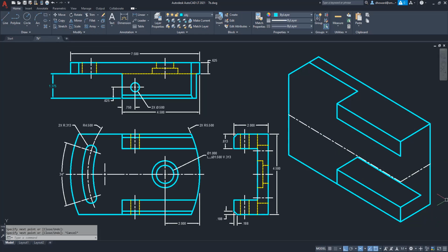That happens to line up with that center line almost perfectly, huh? We can join this with this upper piece if we want by pulling back that distance, which is the 1.375, and then closing it there. Of course, that is not going to stay that way because this side is going to become an arc, but temporarily we can just do that. I'm going to get rid of that center line temporarily because it's kind of getting in the way. Okay, so we have the back, or I should say the right side of this box kind of defined.